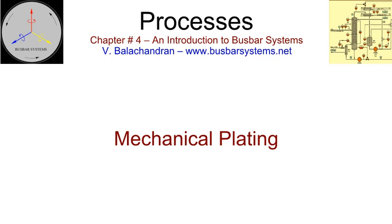It is combined with water, medium, and surface conditioners to establish a light coat of copper. The coated piece is mixed with promoters, accelerators, and powder. The medium cold welds the metal powder to the workpiece through impact in a tumbler. The component has a dull finish which can be improved with water polish. Chromate passivation may be necessary for a thinly coated component.